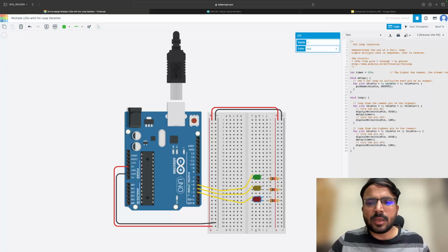We are just repeating the one LED function, driving digital output port 3 as an output and then repeating it for 4 and 5, and driving the values using the inbuilt digitalWrite function, driving it high at 5 volts and then low at 0 volts so that it blinks. There is a voltage difference created across these LEDs and the LED blinks.